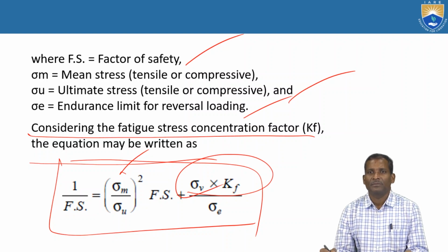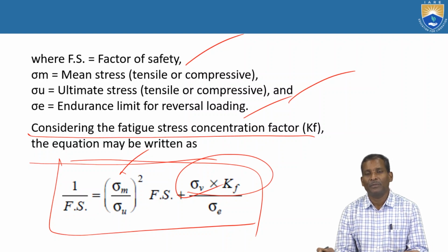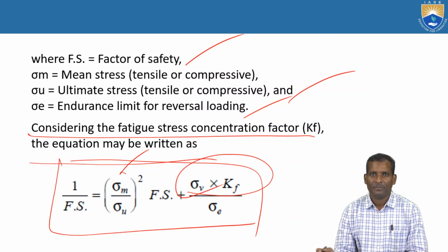Only you are considering the fatigue stress concentration factor, and that factor you should multiply with sigma V, the variable stress.